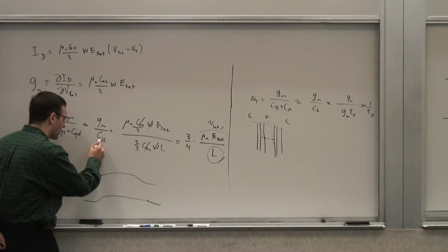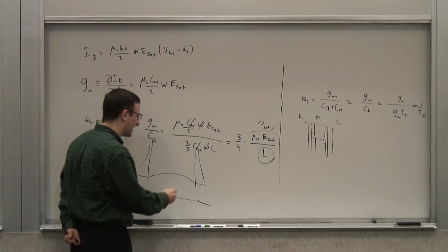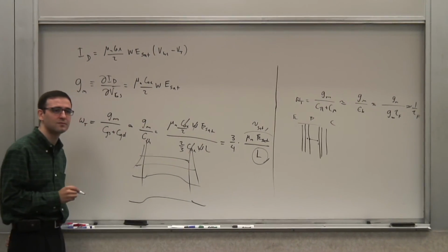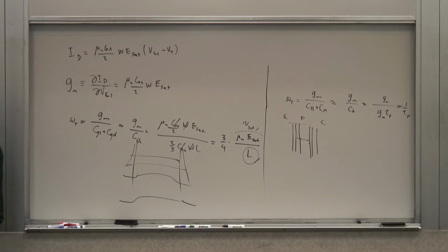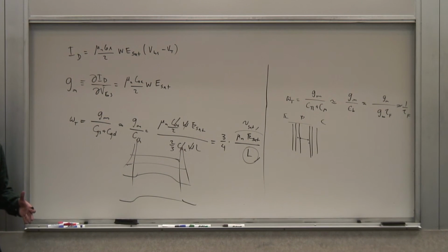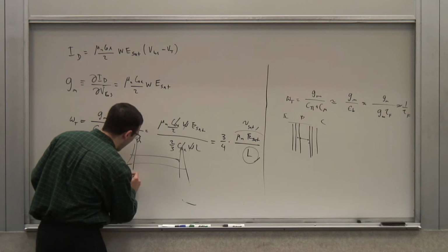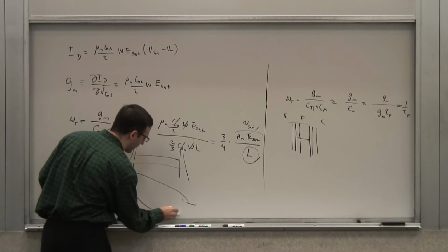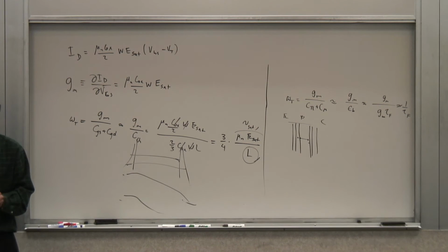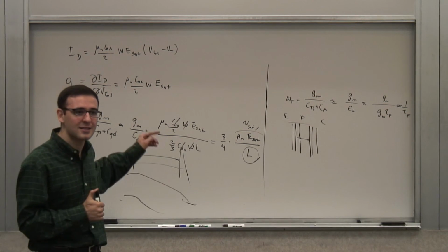So there are plenty of electrons on this side, and there are plenty of electrons on that side, and they're constantly going back and forth, right? But there's no net current in the MOSFET. When you apply an external electric field, though, what happens is that on top of this, you have that drift velocity, which is substantially smaller than this thermal velocity.